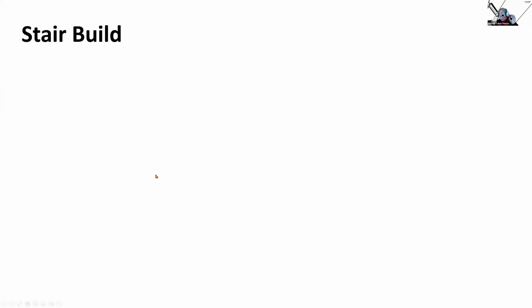So my idea, if you're going to build a stair, now that we've looked at the nitty gritties inside the stairs: first thing I'm going to tell you is copy, paste, and edit. That's what I'm preaching so far. You're going to get this file. You're going to copy, paste, and edit. Or you're going to get it from another project. If you've already got one in another project, go get it. Bam, done. You bring the family over, and then you've got the system family that you can bring in there.